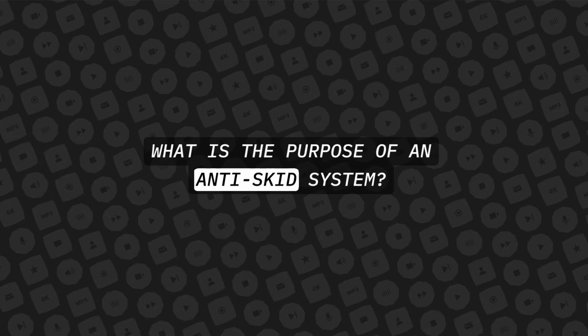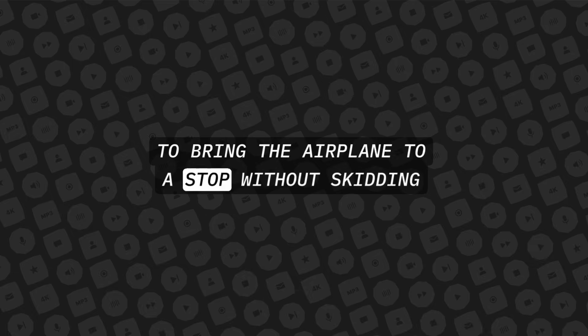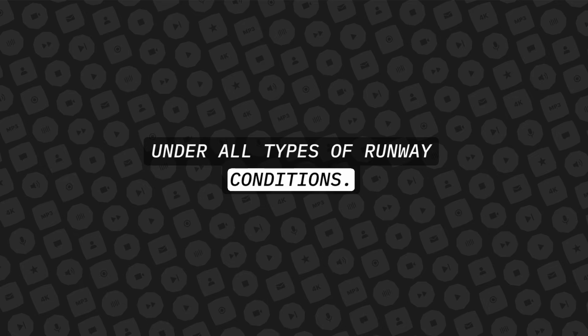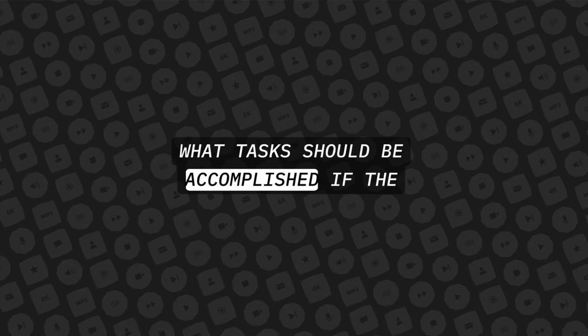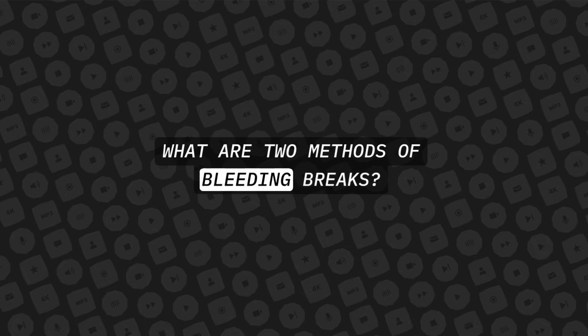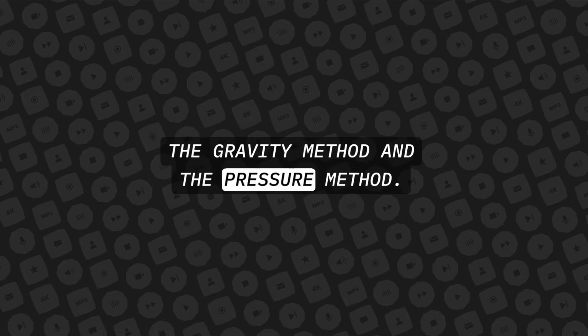What is the purpose of an anti-skid system? To bring the airplane to a stop without skidding by providing the most effective braking power under all types of runway conditions. What task should be accomplished if the aircraft brakes are spongy? The brakes need to be bled. What are two methods of bleeding brakes? The gravity method and the pressure method.